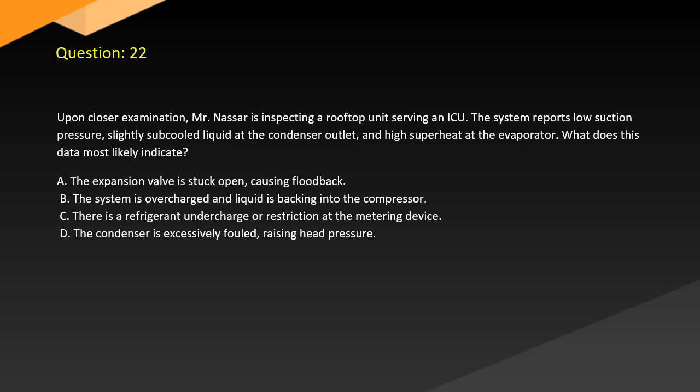A. The expansion valve is stuck open, causing floodback. B. The system is overcharged and liquid is backing into the compressor. C. There is a refrigerant undercharge or restriction at the metering device. D. The condenser is excessively fouled, raising head pressure.